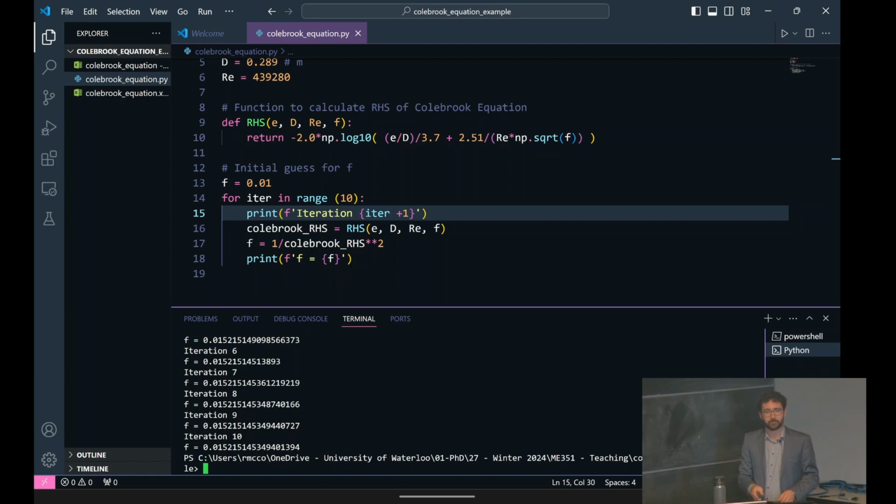Right. Yeah. So pressure is always relative in piping systems, and in incompressible flows in general. It doesn't matter if you have a super, super high pressure, the pressure drop is the same regardless of what P1 is, for example. Okay. Yep. How do elbows, T's affect this?